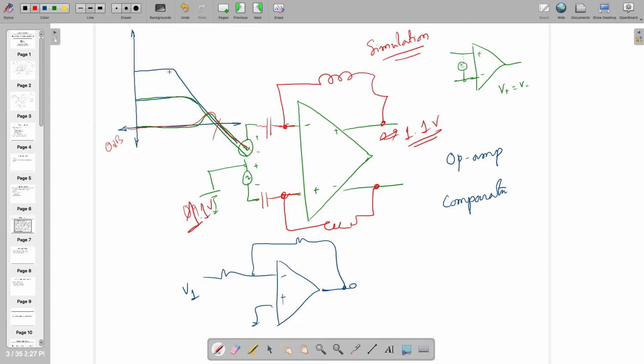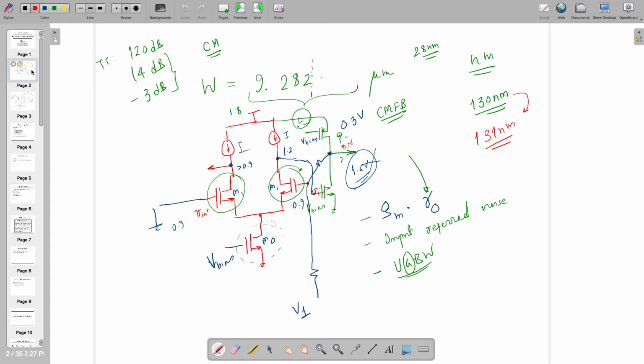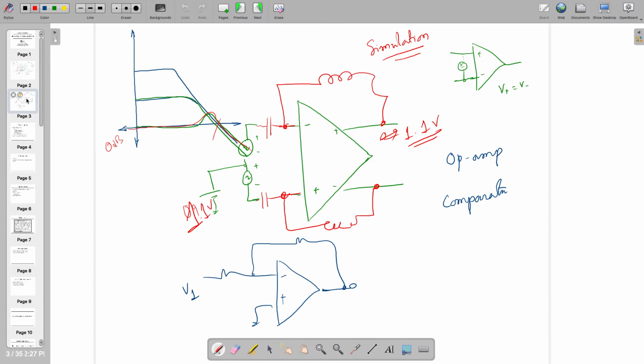So you need to simulate it using inductors and capacitors. If you are not doing that, maybe your answer will change. I hope you are doing that. If not, I'm telling you every time and you are making the same mistake, then I don't know. You need to add something like 1 Henry. Okay, it's a big inductor, but we are not going to tap it out ever. This is just a simulation technique through which you are making a short at the low frequency. If you take something else, then the answer will be different.